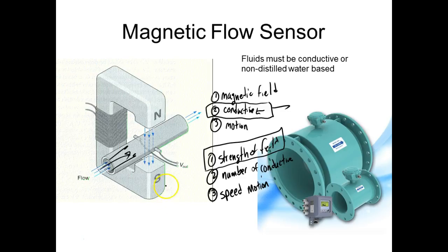But the only opposition we have is the tubes. The sensor itself does not measure by a pressure differential. It does not measure by a pressure. The sensor itself creates no pressure loss. Right? Absolutely no pressure loss. The sensor, now the tubing, we can't do away with the tubing. We can't do away with the valves that control the direction and stuff like that. But you're right. Flow direction doesn't matter.